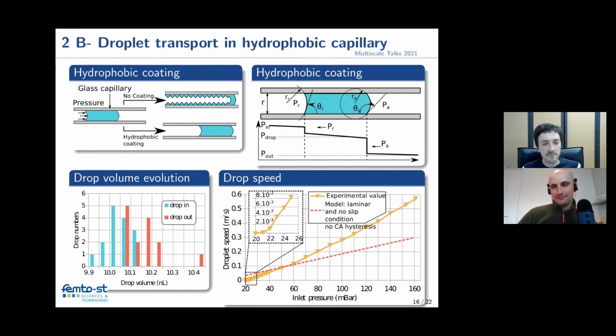In fact, sending a small droplet in a hydrophobic tube or capillary, we didn't expect it, but it was really interesting. So I was really happy to read about this. And as I understand, the main hypothesis is that there is a slipping on the boundary, and so viscous fluids advance more as a plug than as a parabolic flow, if I understand correctly.